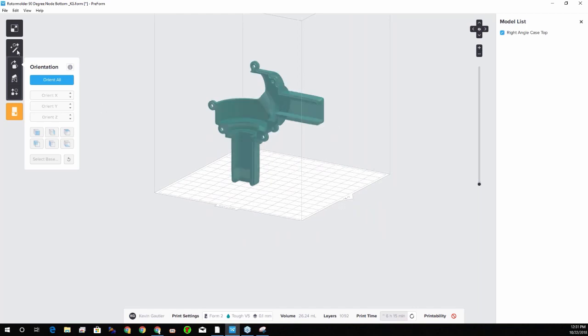We have a quick, convenient magic wand feature called One-Click 3D Print that will automatically orient, support, and send your part to the printer. This is our sort of easiest way. I'm going to show you more of a professional-level user's way of supporting the parts, the sort of better way.